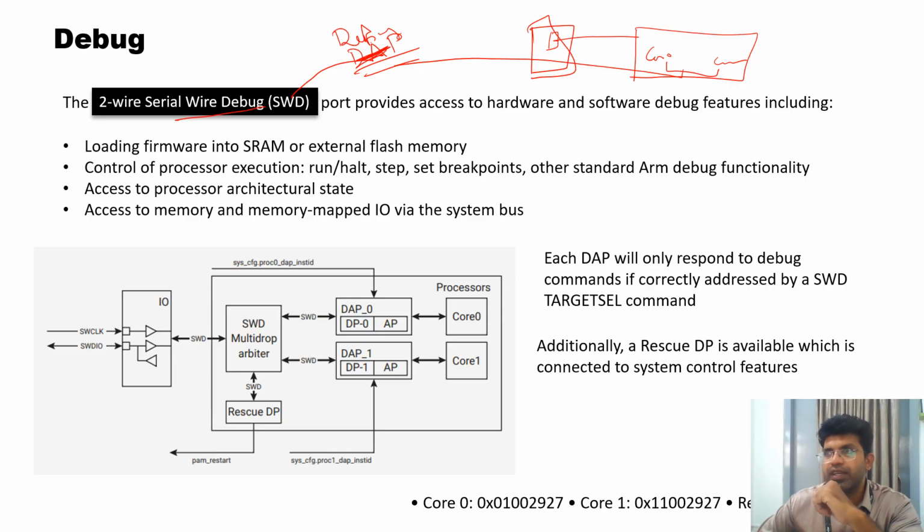So what they're saying is I can directly talk to my microprocessor. We are actually talking about a microcontroller, but for debugging I can directly talk to the microprocessor and see how it is being performed, right? So if it is like writing the main firmware to the SRAM, or if I want to set breakpoints in my microcontroller and see how the firmware is working to a particular level, to run, to halt, and other functions that are available in these ARM controllers, I can perform that.